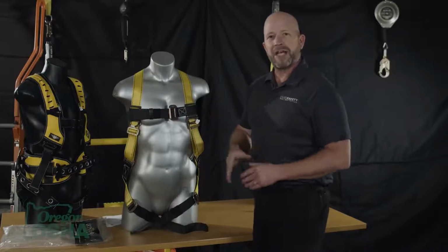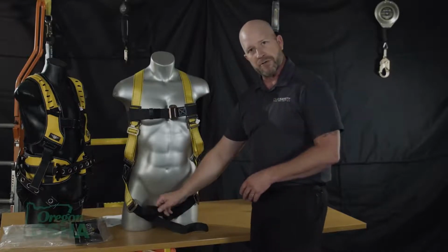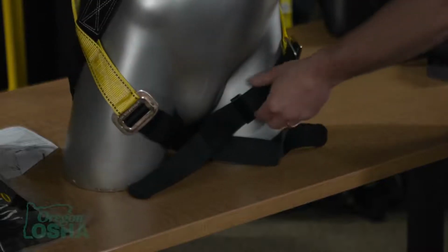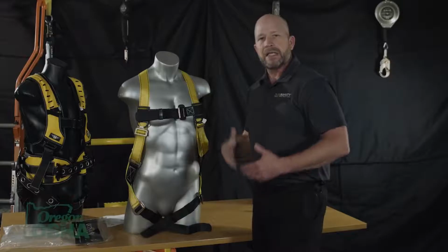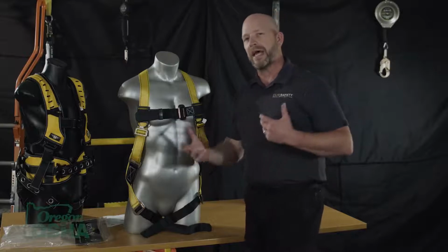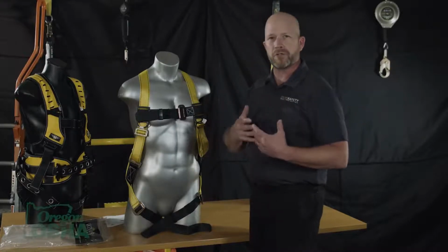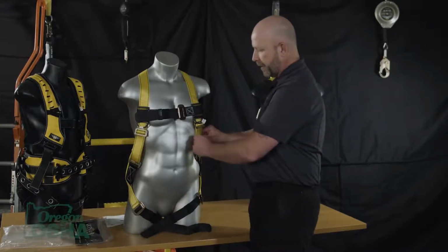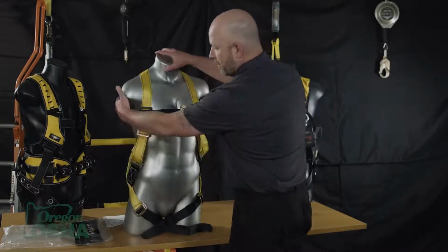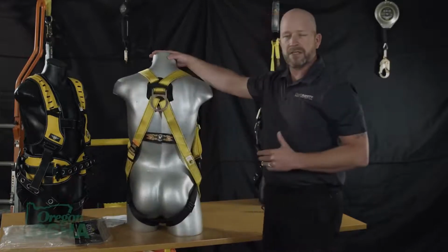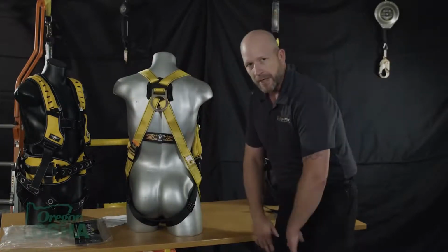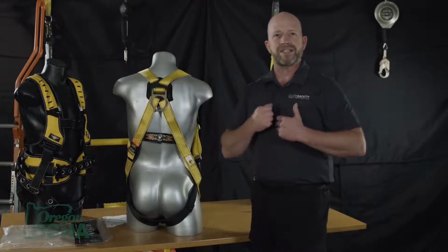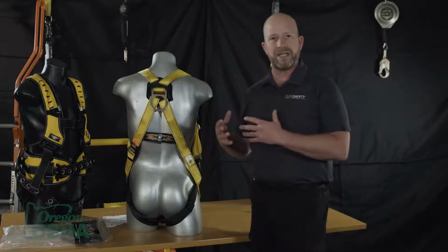Couple final checks once we have it fitted. If there are extra straps, ensure that you tuck them through the buckles that are generally provided on most harnesses so that you can slide it through. The idea is we don't want them dangling around where they can catch onto equipment or other tools or sharp objects, which can pull us or dislodge us. So once you tuck all of those away appropriately, depending on the design of the harness, then we want to do the final checks. Have the worker stretch their arms, bend over, flex, do the things that they would normally do in a work environment to assure that it's not restricting them from doing what they need to do.